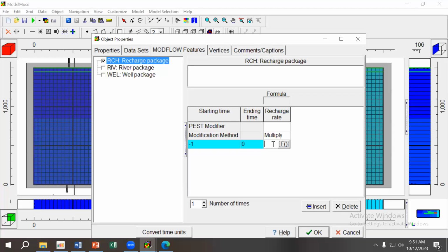Remember, not all this rainfall will infiltrate the subsurface, and not all the water that infiltrates the subsurface will recharge the groundwater. So if you assume that 20% of your rainfall will recharge the subsurface, then you get 0.8. So that's how I got this value.